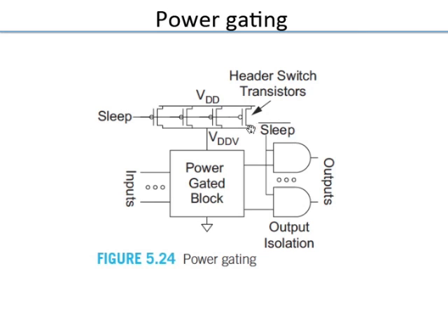So you could do things like that, higher threshold, etc. And one thing you have to watch, it's a tricky problem, because of the current consumption of this gated block. You have to size this such that the IR drop across this is kept small. But what is the I to use to calculate the IR drop? I is time varying. If you remember the current drawn by an inverter when it switches, the current is consumed only during the switching.